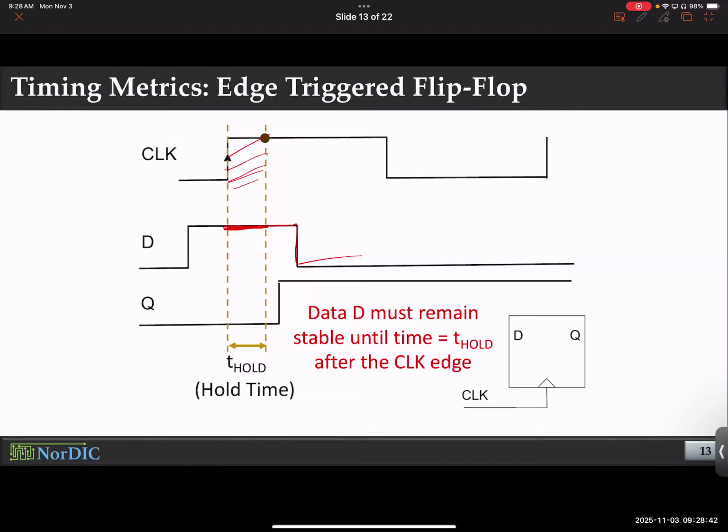You suddenly go to 0. And while it is charging, it starts discharging again. So it's not going to complete anything. It will not go to VDD. It will not go back to 0. It will be stuck somewhere in the middle. Does that make sense? That's what leads to disaster, because digital electronics doesn't recognize anything between 0 and 1. There has to be either 0, and VDD essentially means 1. Okay? It has to be 0 and 1.